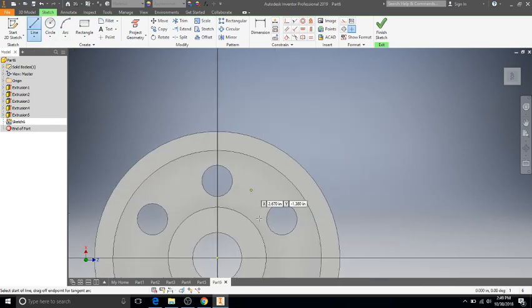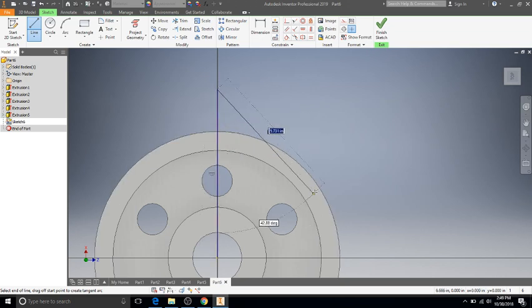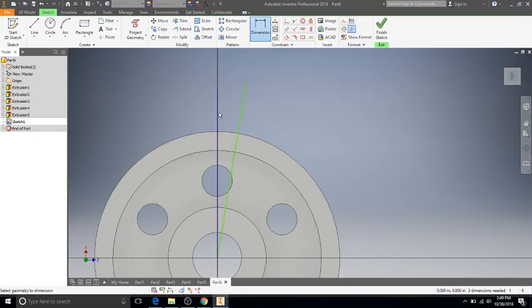So how do we do that? We set our line. I'm going to draw a construction line that comes out to this edge. And you know what, let's go a little bit further. These are construction lines, it's not the biggest deal. Grab the line tool again, come on out, draw it, just a construction line, doesn't have to be perfect. So what I'm going to do is set the dimension between these two lines to be 7.66 degrees, and then it squeezes in. So I should be able to fit 47 of those gaps around the edge.